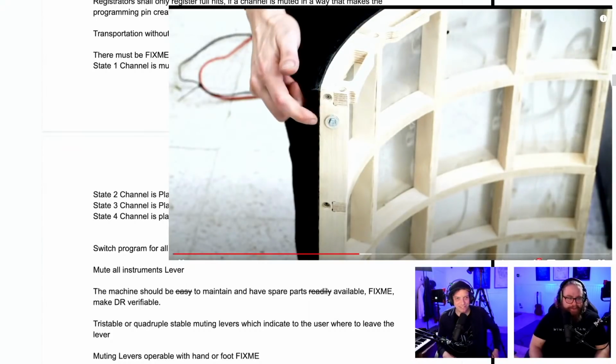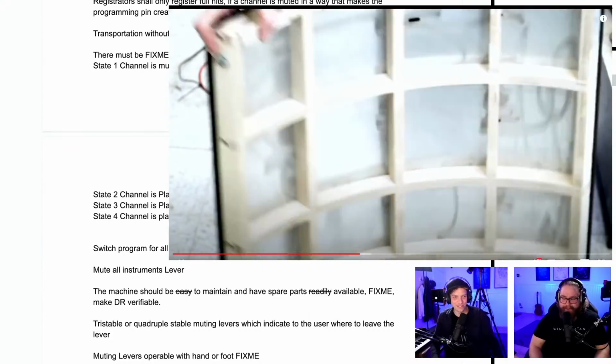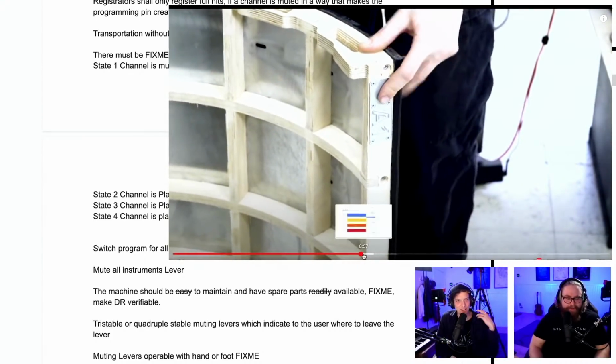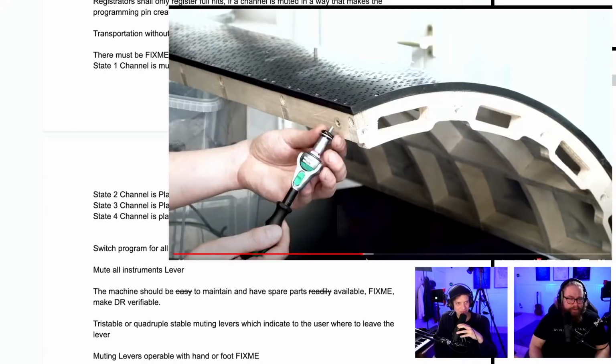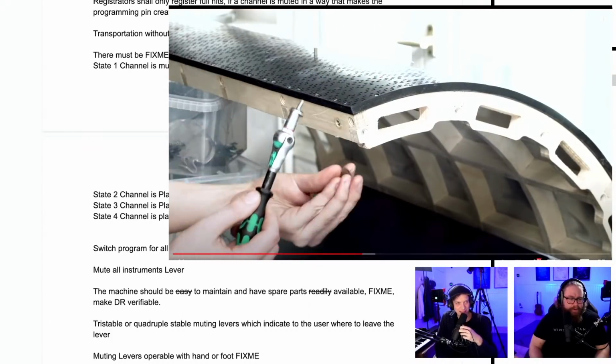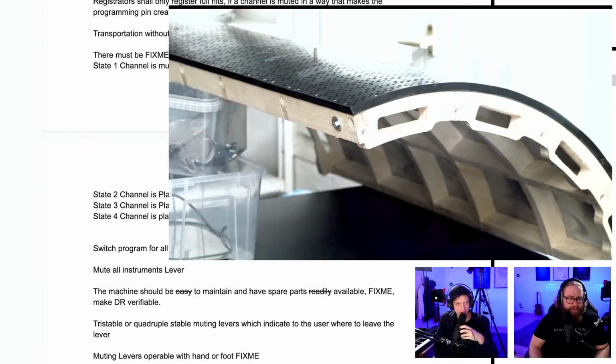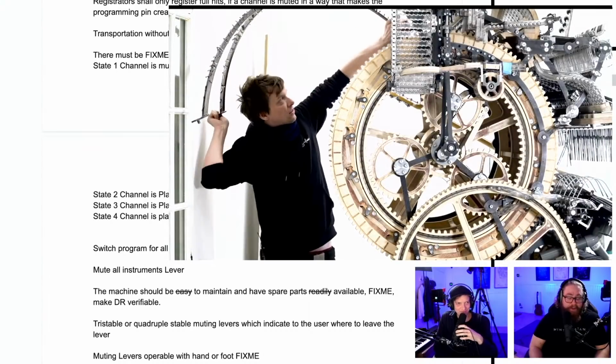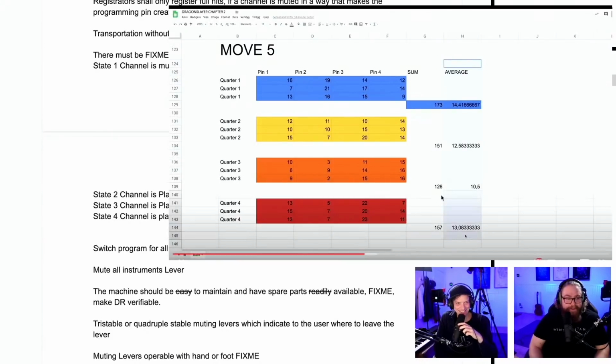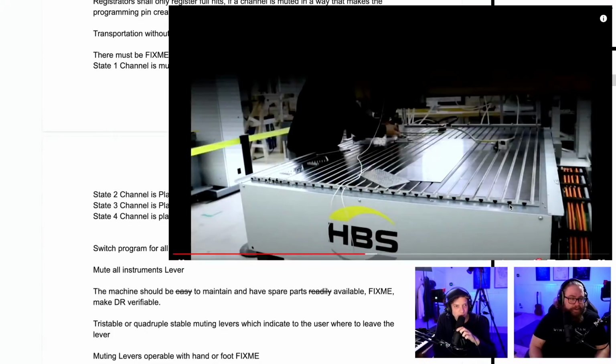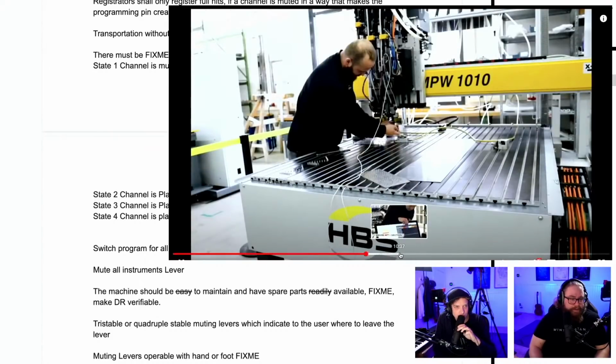Shim washers. Oh, I feel sorry for myself. The bolt is pointing against the plate on the neighboring programming section. The shim washers are 0.1 millimeter thin. So in theory, I should be able to slide the programming sections in 0.1 millimeter increments. I ended up doing 5 tests, taking all the programming sections off and altering the shim washers before I got to